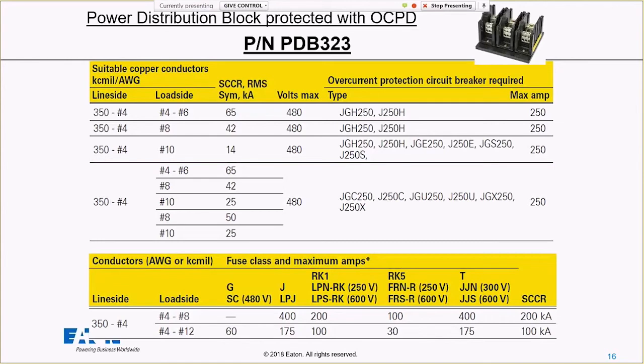A power distribution block is going to have a default rating of 10 kA. If you remember from last week, that chart, it's a default rating of 10 kA, and then changing upstream depending on what we're using. So the good news is a lot of the Bussmann power distribution blocks do have ratings with some breakers. They have it with multiple manufacturers of breakers. The one I'm showing here is Eaton, but we have them listed with other manufacturers of breakers as well.